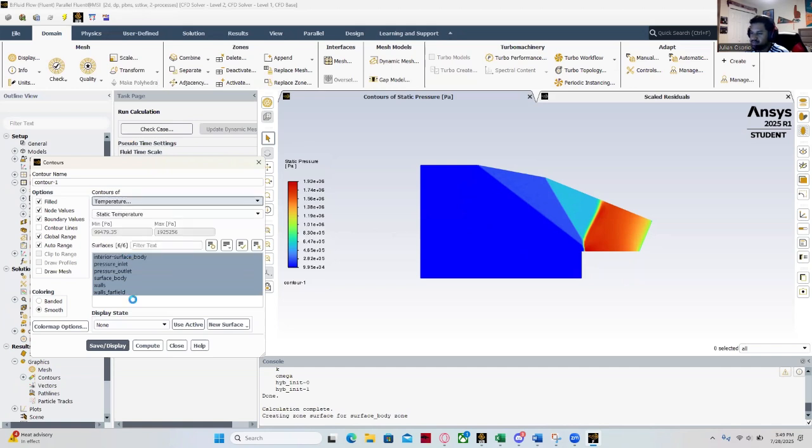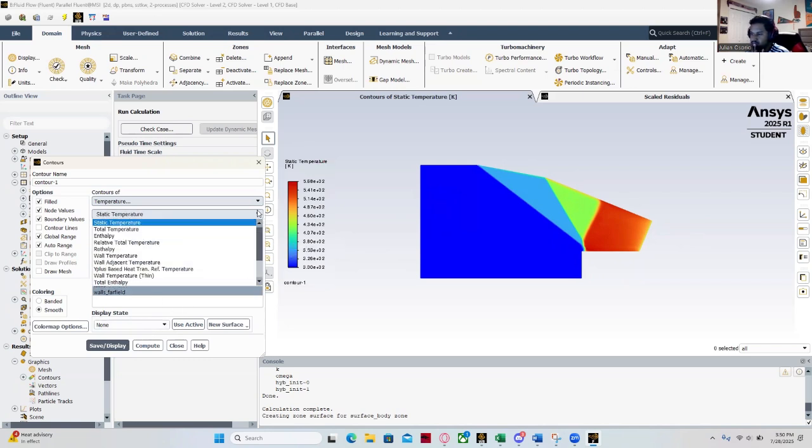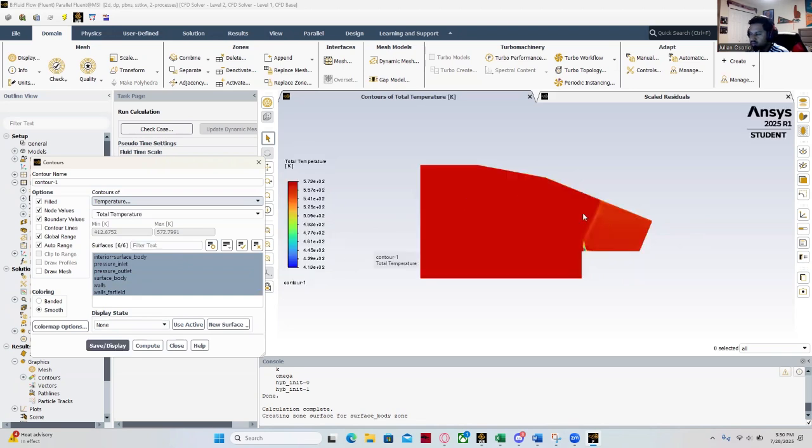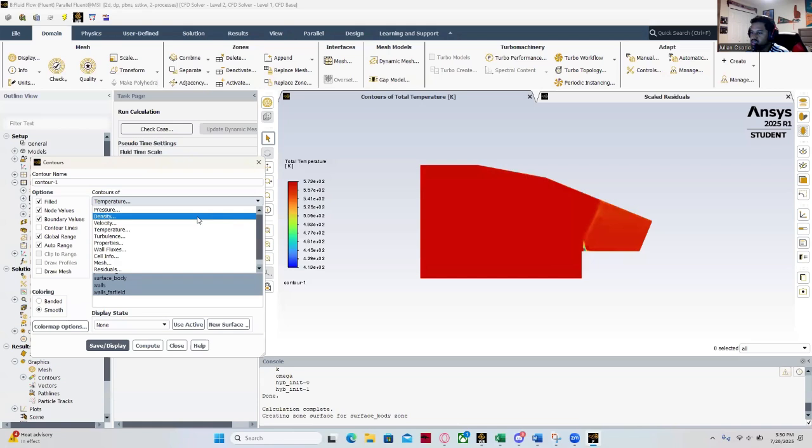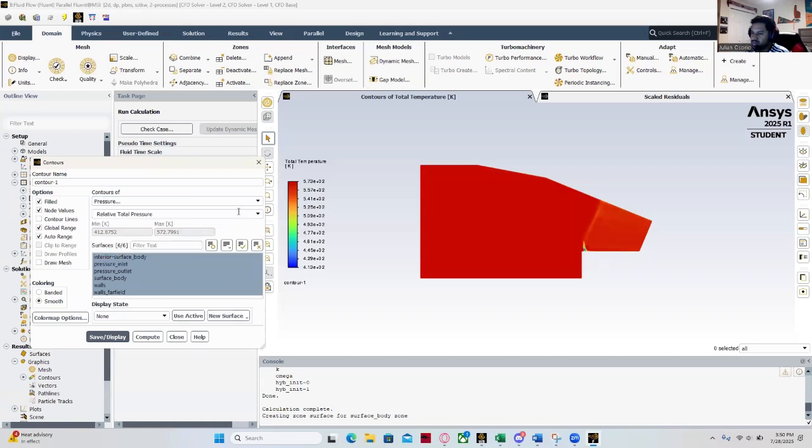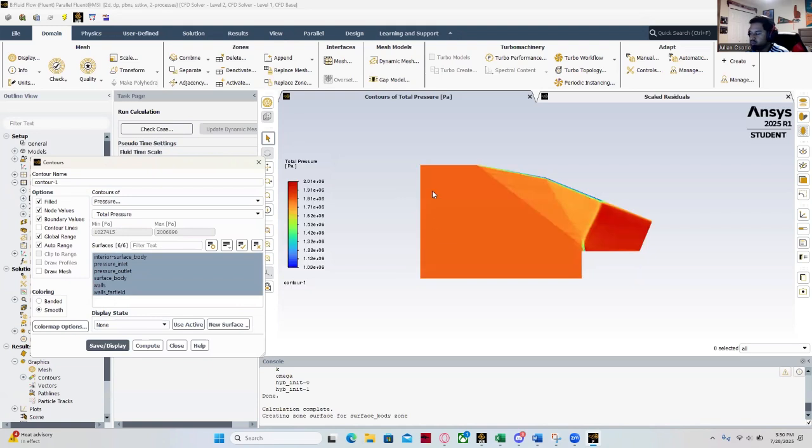Same as the temperature. You see, starts lower temperature as oblique shocks occur. Temperature increases. Not too much, but it's noticeable. Total temperature is about pretty much constant throughout, as stagnation temperature doesn't really change due to shocks. The total pressure is going to look like this. Seems about right. Yep, as pressure recovery ratios across a shock always increases.